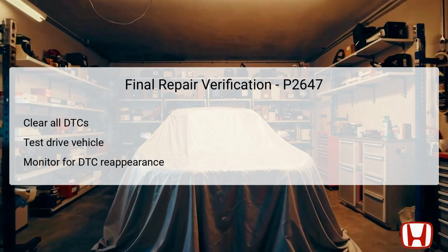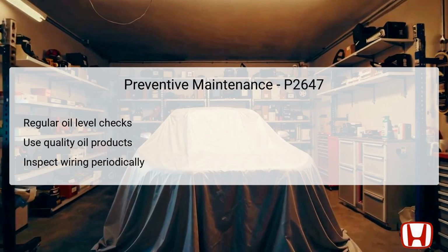It's important to conduct various driving scenarios to confirm that the VVT system is operating as expected, without triggering DTC P2647 again. Should the DTC reappear post-repair, further investigation may be necessary to trace other potential issues that were overlooked previously. To help prevent issues that might lead to DTC P2647 in the future, consistent preventive maintenance is essential.